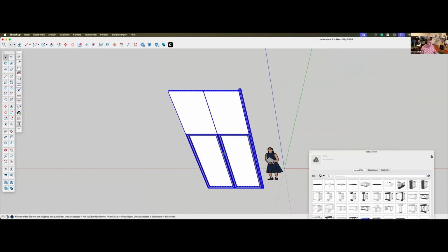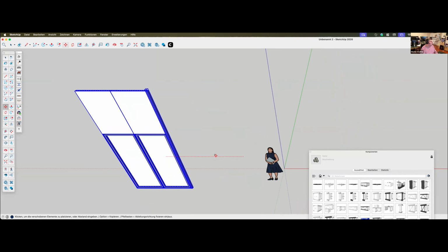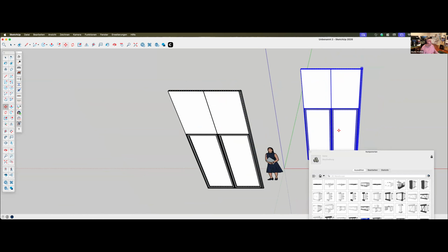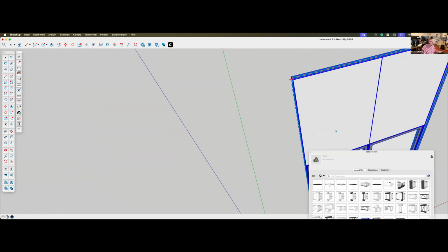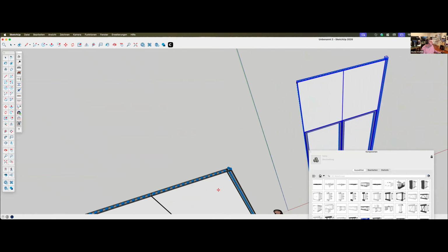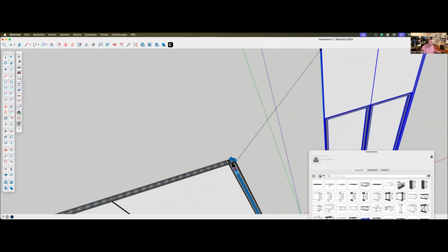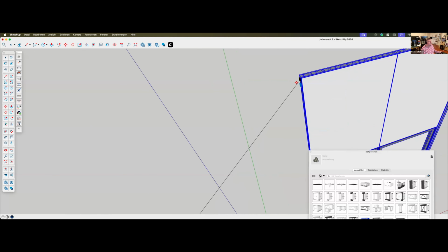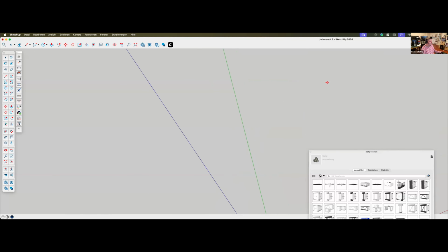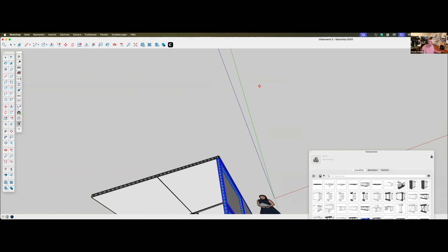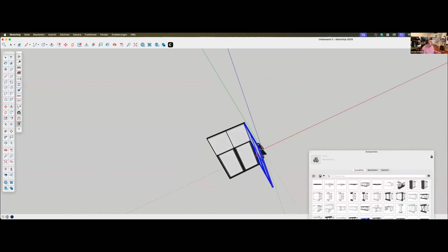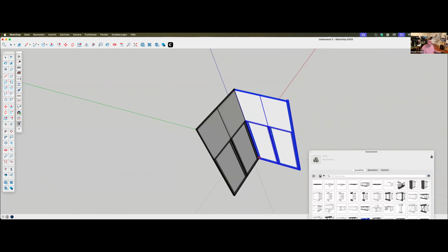So I'm selecting all of this. I'm duplicating this with the Alt key. And now I also can snap multiple things at the same time. For this, I'm clicking the snapping tool in here with this, selecting this thing, one, and going into here, and then say from here to here. Okay, enter. And then when zooming out in here, you also see that you have this wall aligned to this.